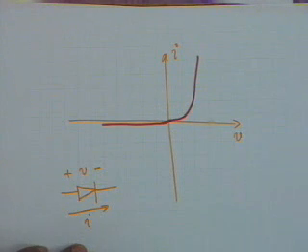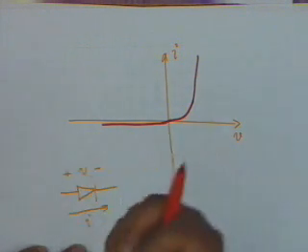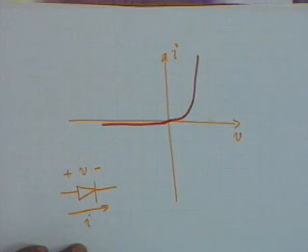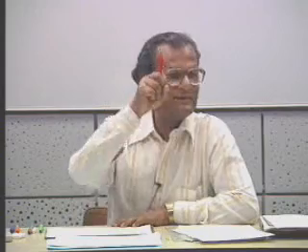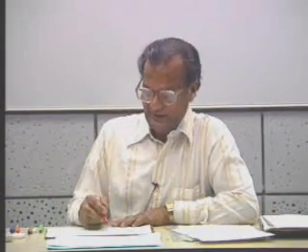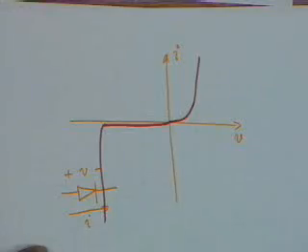a limit to everything. Enough is enough. It cannot stand for a long time, because as you increase the reverse bias, you also increase the velocity of the minority carriers, and the minority carriers say we can go up to this much, then they acquire so much energy that they collide with fixed atoms and break them. And then what happens is an avalanche. The current suddenly increases.